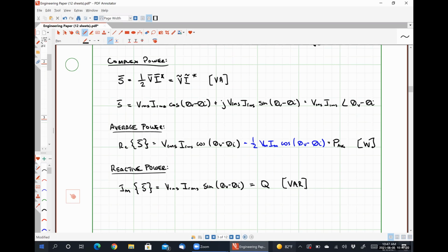When we were talking about the instantaneous power, I guess it might have been yesterday actually, or maybe the day before that, I can't quite remember. We saw that the average power absorbed by a capacitor and the average power absorbed by an inductor was 0. We observed that exactly half of the time a capacitor and an inductor absorbs power, and exactly half of the time the capacitor and inductor supplies power back to the source, okay? So the reactive power represents that portion of the complex power.